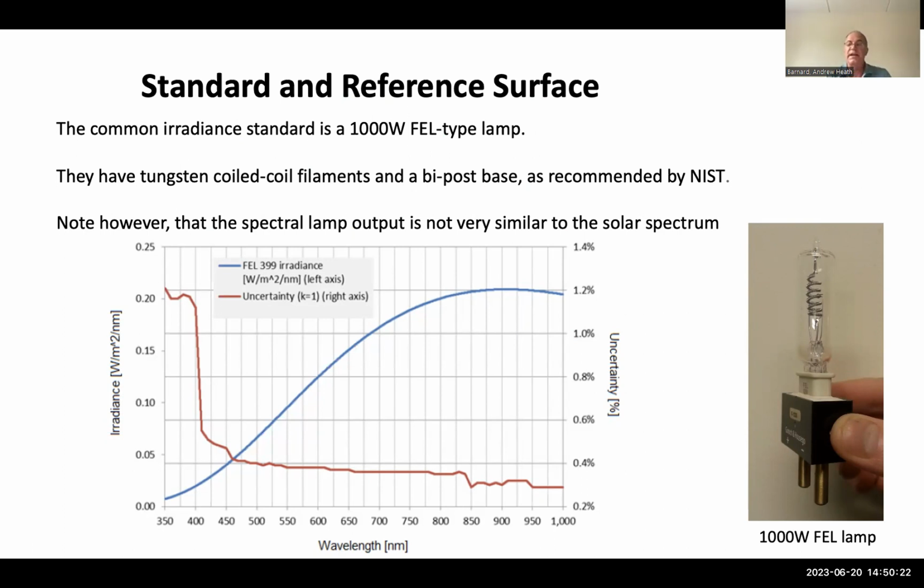It's a very bright light, 1,000 watts. It does a lot of heating, but it's also highly sensitive in the calibration process to any dust or fingers on the actual glass element of it. So you have to be very, very careful never to touch that. Otherwise, your calibrations are going to be way off really quickly.